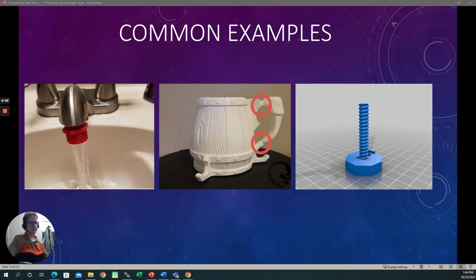So if you ever had something that you were going to use in the water, we really highly suggest that you increase your shell count on that. And again, all of these concepts that we've talked about so far are things that you do not do while you're modeling an object in CAD. This is after you bring your object into the library, and that's where we can tell that object how thick to be on the skin or the infill or whatnot.